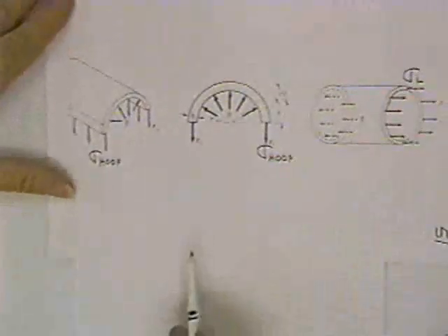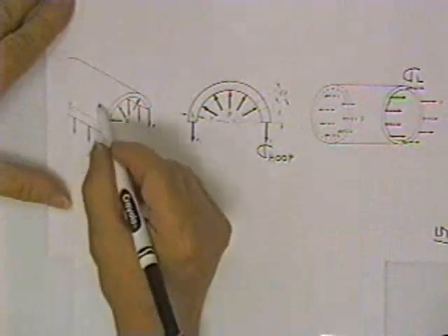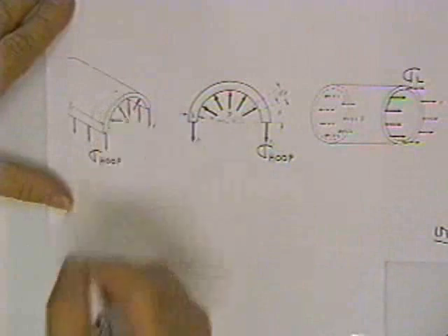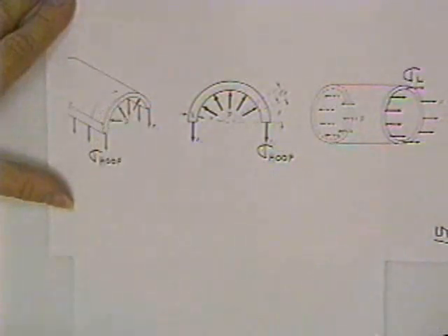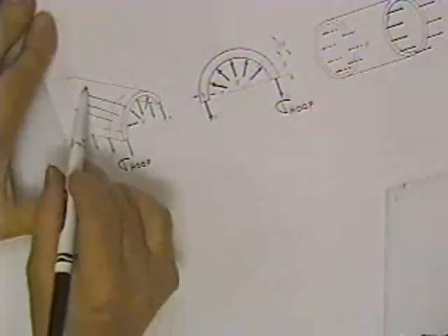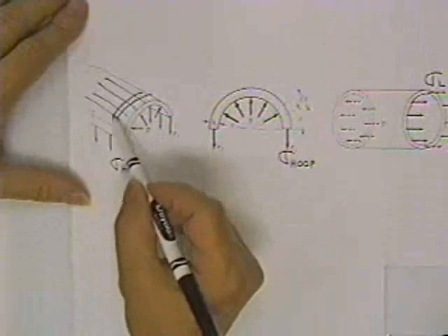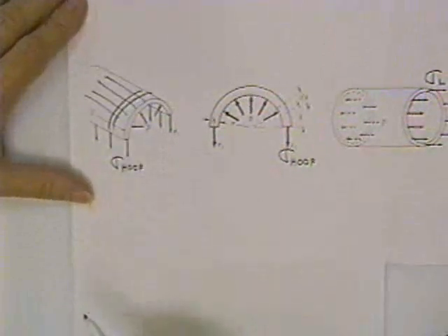Here is a picture of what half a tank looks like. You'll notice it has hoop stresses. The hoop stresses are running in the hoop direction. They called them hoop stresses because they used to make these things out of barrel staves. They put beer in them, and they had to put steel bands around them. They had to put hoops around them to hold the barrel together.